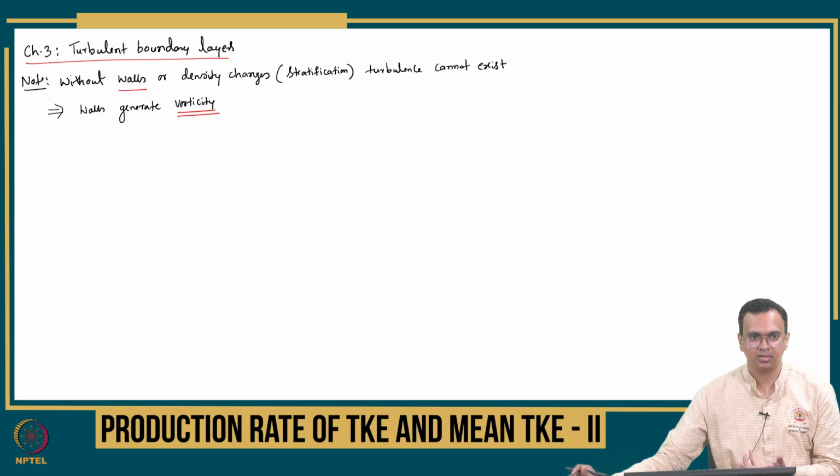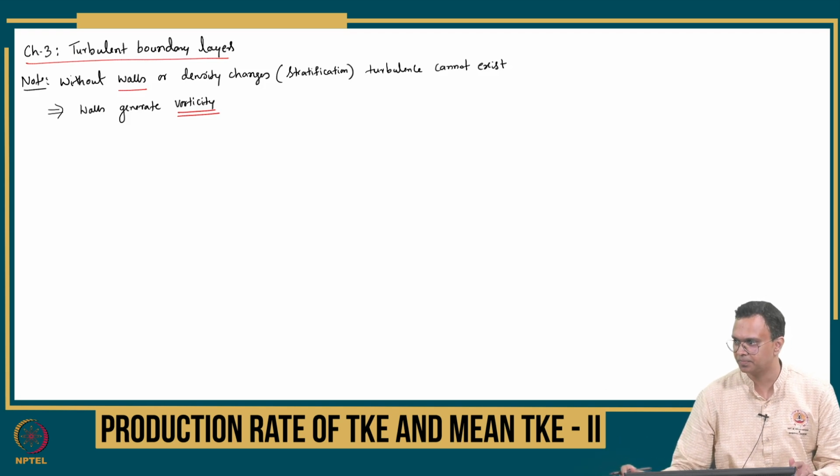and the question is, is it turbulent or laminar? That is a question to you. Data is given. I told you all oscillating, fluctuating systems don't have to be turbulent, right? We saw that the financial stocks are also exhibiting randomness, and randomness is established in many signals. Just because it is random doesn't mean that it is turbulent. Turbulence is also a random process, but all random processes are not turbulent. So how do you find out whether the flow is turbulent or laminar? I told you in one of the classes.